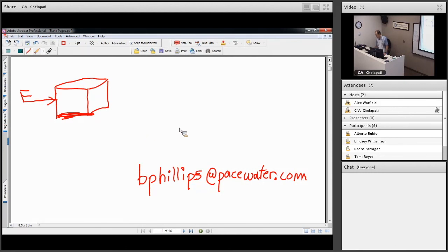From the bottom here, the fluid actually sticks to the solid. That's one of the basic properties of fluid motion: at a surface, right at that boundary condition, fluids stick to it. If you have a ship moving along, the particle of water right next to the ship is moving at the velocity of the ship.